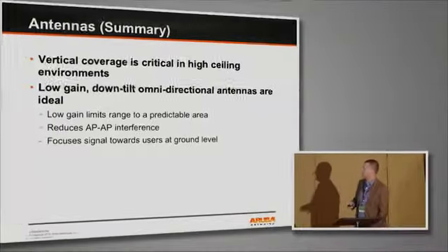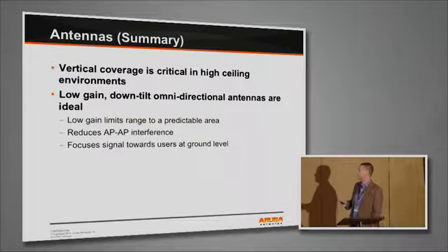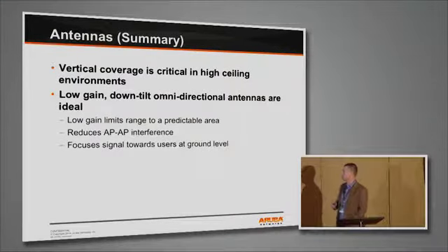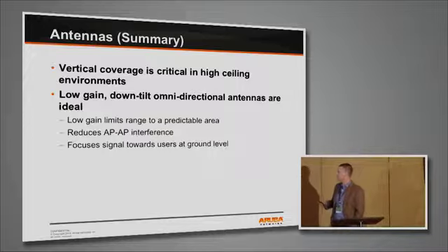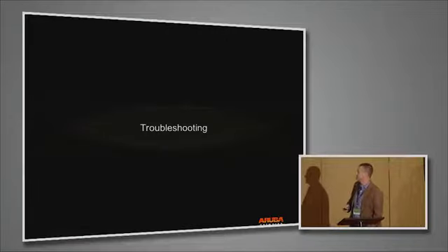So, again, from an antenna perspective, if it's mostly vertical coverage, if it's not the freezer, I'm typically looking for a high ceiling, a low gain down tilt Omni. And I think we pretty much already covered the reasons why there.